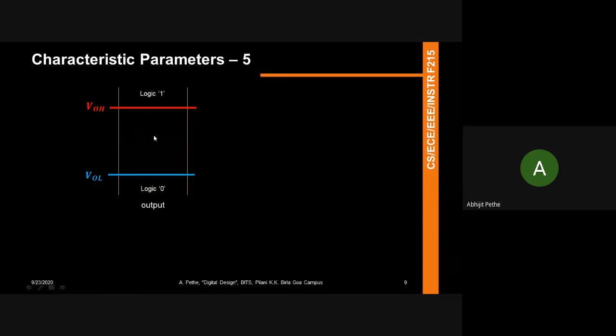So what will normally happen in things like this is, in your circuit, there might be some freak nodes which will do this, and that's a bad design sign. So whenever you design your system, you have to ensure that at no point should the voltage at any node in the circuit get into this regime, because that voltage doesn't have a logical meaning, right? Now let's look at the input side. This voltage range is sometimes known as a disallowed range. So you don't want voltages at any node, especially the output, to sit in this range.